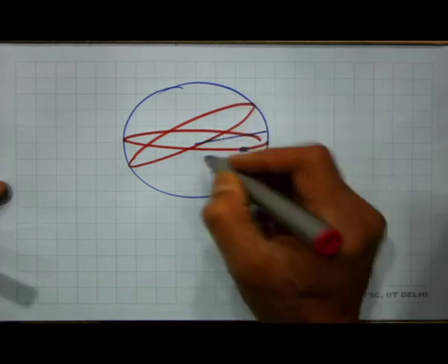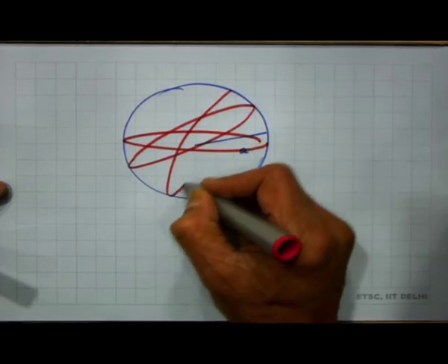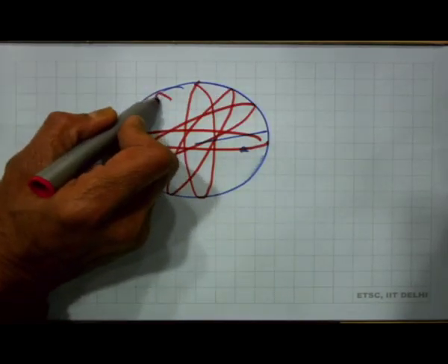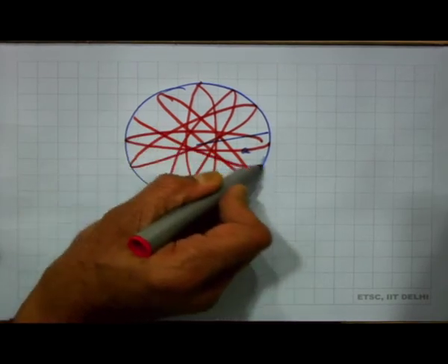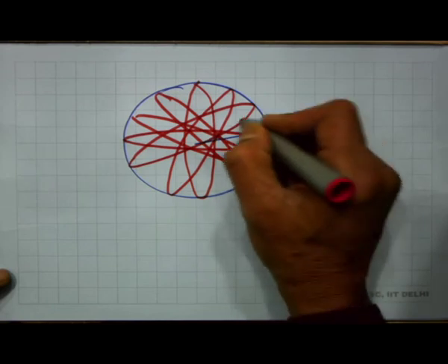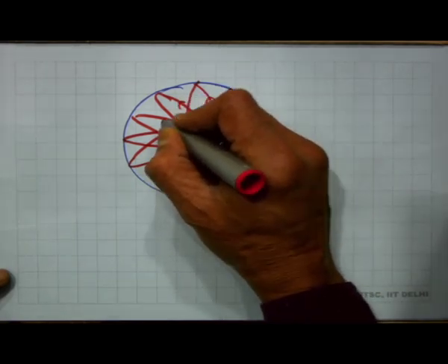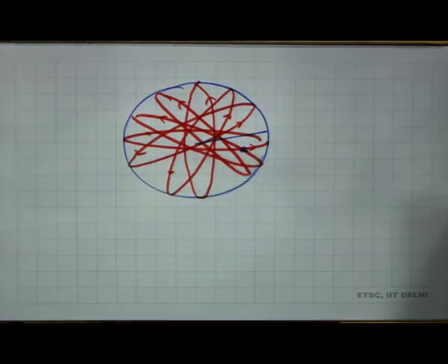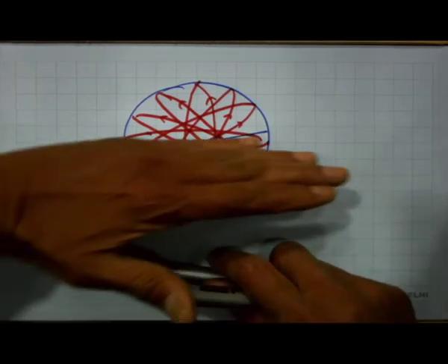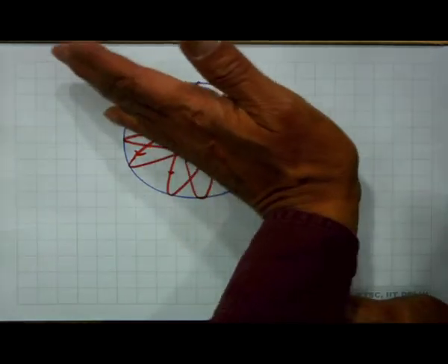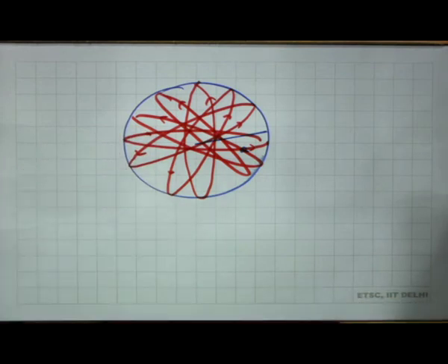So, this angle is 30 degrees, then another winding comes here at 60 degrees, another winding comes here at 90 degrees, then another winding comes here at 120 degrees and another winding comes here at 150 degrees. So, there are 6 windings. Each of them is carrying current. So, I have 6 windings, each of them rotated by 30 degrees. So, this is horizontal, next 30 degrees, 60, 90, 120, 150 degrees, and then you have the original one which is at 180 degrees.